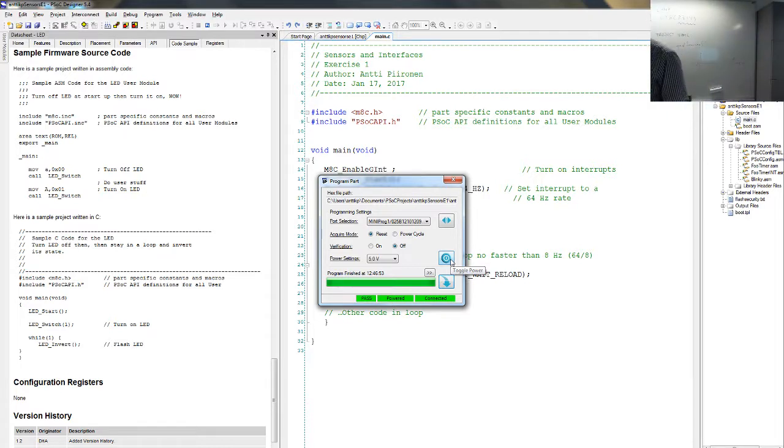All right, so the LED is the easiest way of putting any I/O action. If you want to drive a transistor, for example, you just put an LED module there to drive a signal to some pin, and then you have the external transistor. Just like in my infamous electronic lore, there's only one driving transistor for that motor. The motor takes about 200 milliamps of current when you run it, that vibrator motor, and basically you need a transistor to run it.